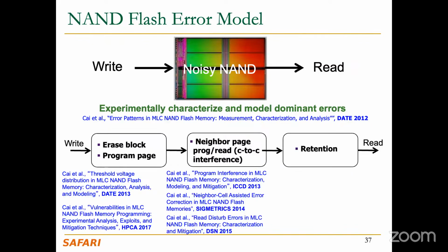And essentially you also have this retention error: if you write to your flash memory and don't read it for, let's say, 3 years, basically good luck. You may not be able to recover your data. Usually it doesn't happen with nowadays SSDs, because they have a lot of internal management tasks that are refreshing the data.